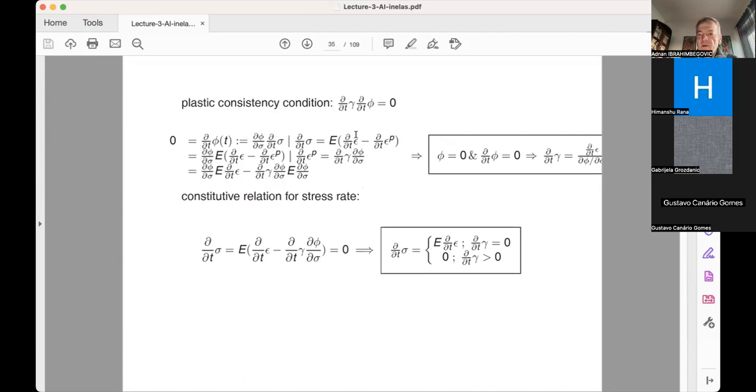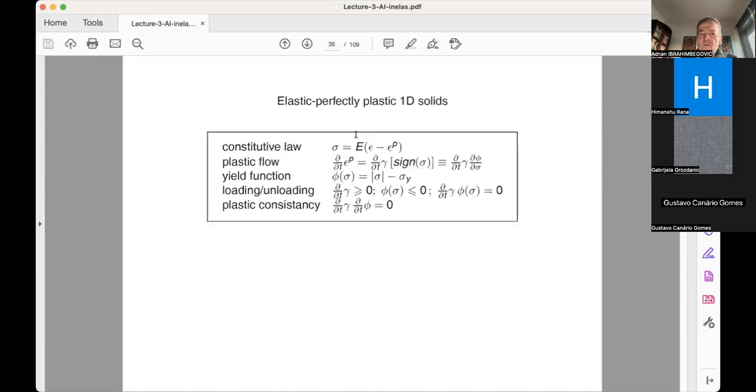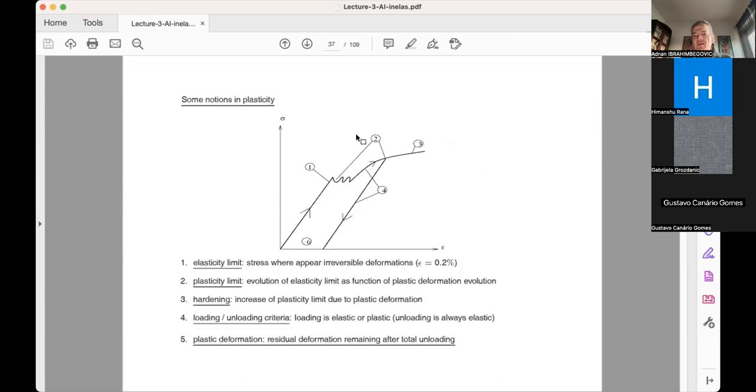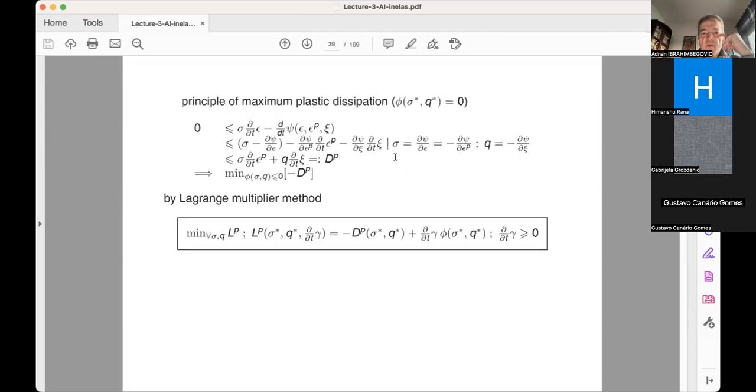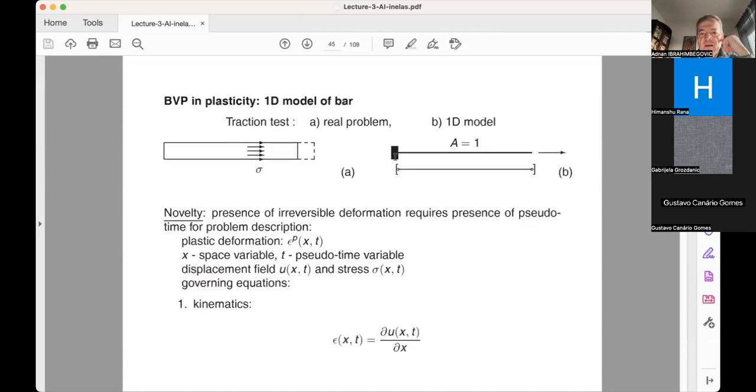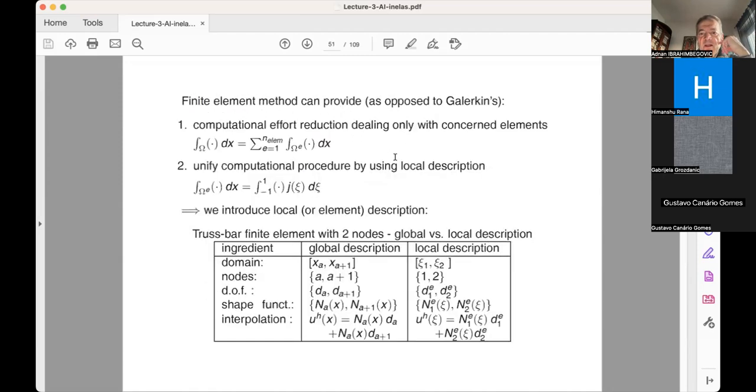So for the elastoplasticity, it was a very simple case. It is like stress is linearly proportional to the strain or it's constant. And then we made it more interesting to be closer to real type of behavior by introducing linear hardening and then explain the same steps to apply and also explain how to get computation with the finite element method.